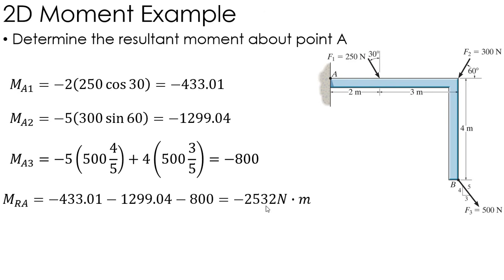And again, I just break each force up into the components, figure out which is the perpendicular component, and use that to figure out the moment of each one, then sum up each moment to figure out the total resultant moment of those three forces added together.